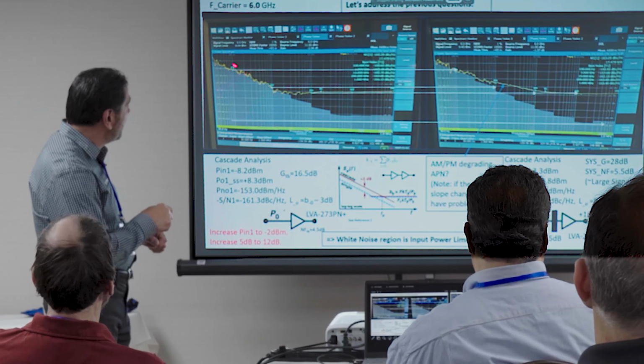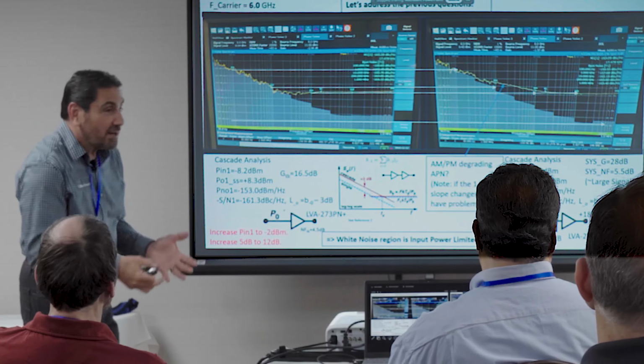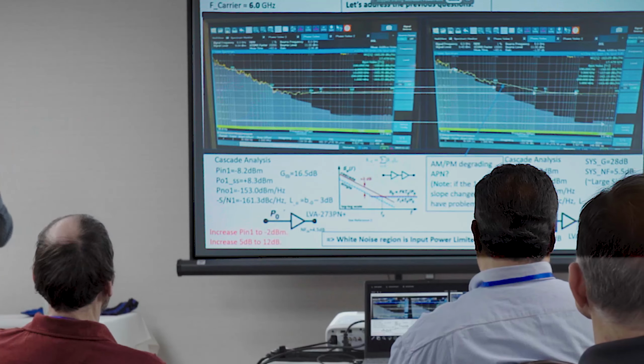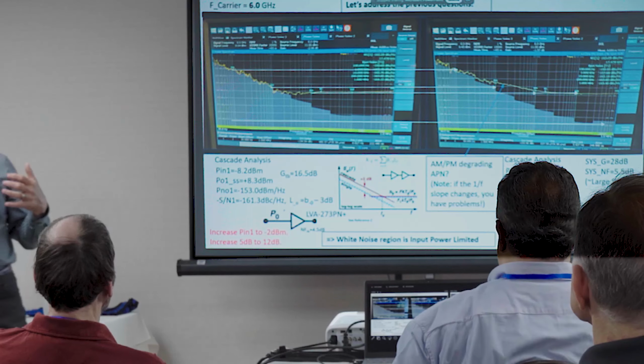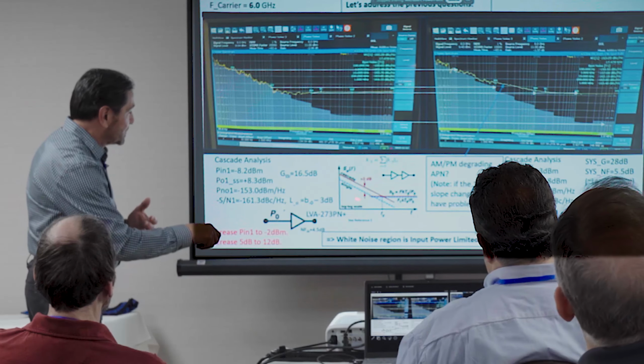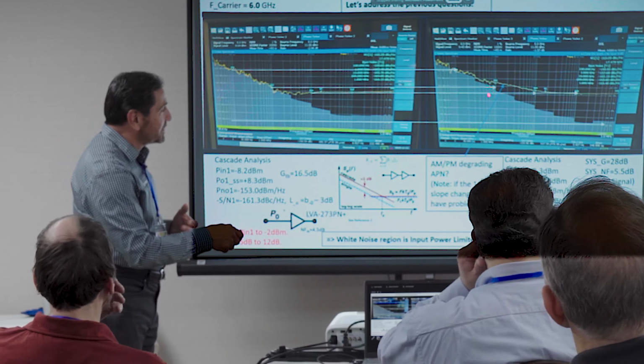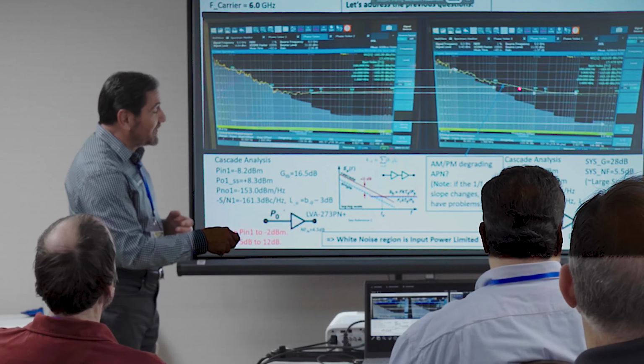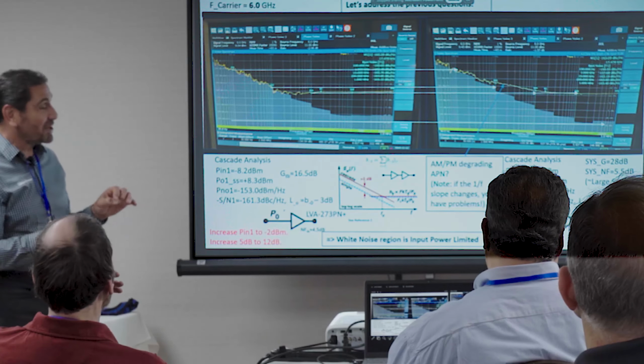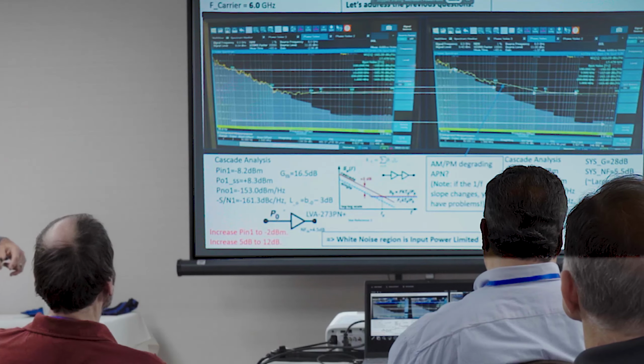See how it's starting to come off the noise floor here? Starting to rise. That's that 3 dB increase in 1/F noise that Professor Rubiola predicts here. So you're seeing it here. You want to watch this region though. If you start getting crazy, you're overdriving something, and we'll see what happens then.